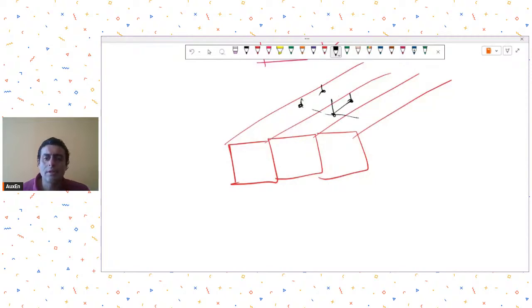point loads like this, and check for the possibility that the next axle can it be there or it will lie outside. And then for such a possibility, you may have to manually work out what is the position that gives you the worst effect. Okay, so I think such a thing can be done. First try to study what's happening and then take this decision.